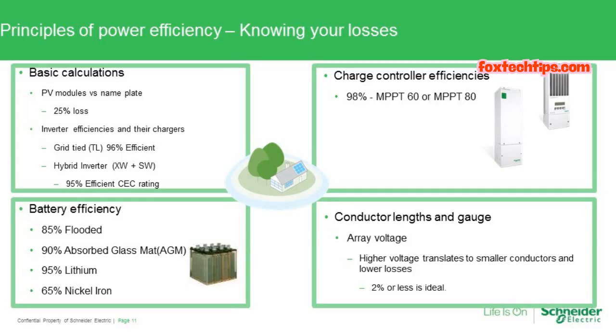Beyond that, of course, we have to understand that the inverter consumes a little bit of power on its own during that conversion process from energy stored DC to AC. And so that definitely needs to be taken into account when doing the calculations. If, for example, you're trying to do an AC coupled system and understanding where that power is going during the daytime versus the nighttime, we'll jump a little bit into that, but it could be that 98% efficiency off of the grid tie inverter is the number that you would end up looking at if primary consumption's during that time.